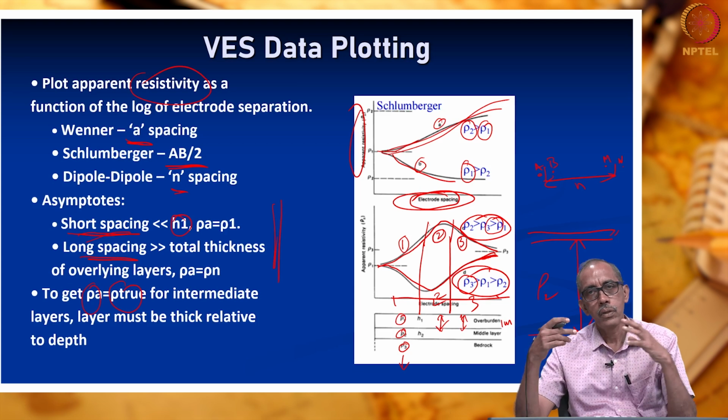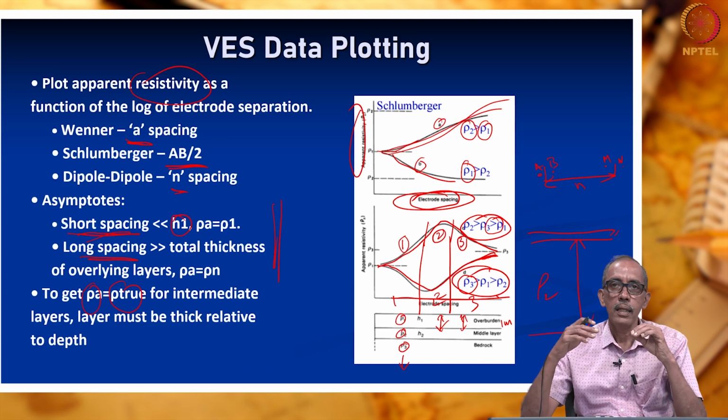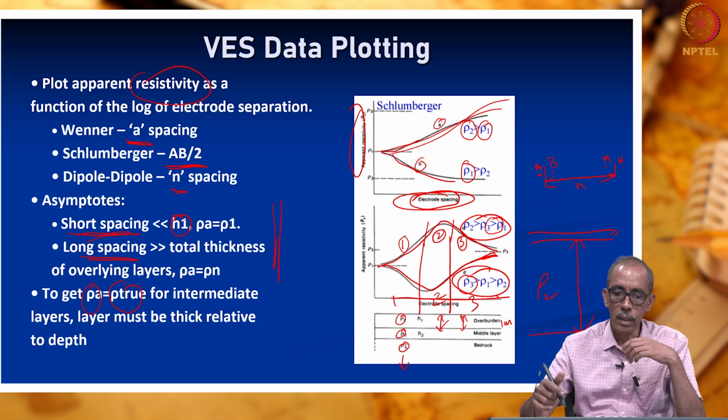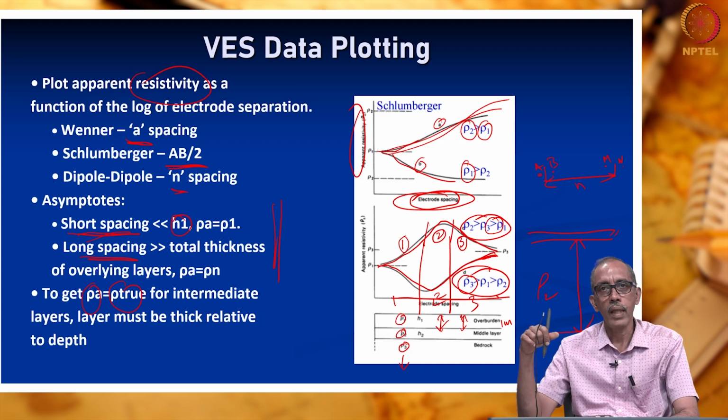Thus, in vertical electrical sounding, we are obtaining the data of resistivity with respect to depth. How do we say depth? Indirectly, electrode spacing refers to depth. So, that is what we have achieved. Interpretation is based on drawing a relationship between electrode spacing and the corresponding apparent resistivity.